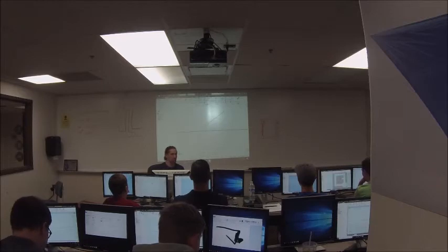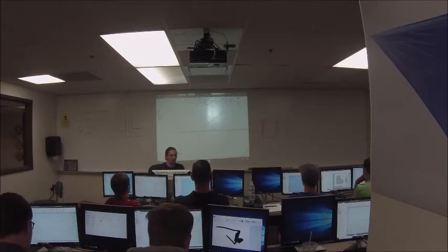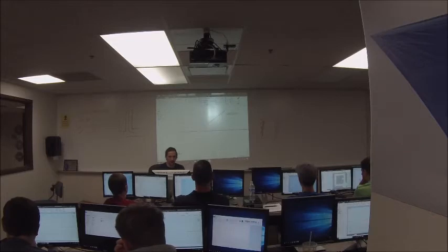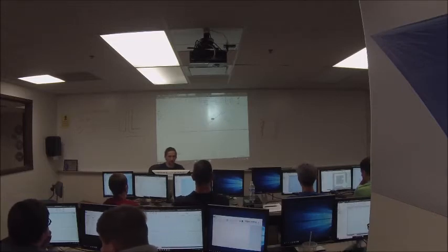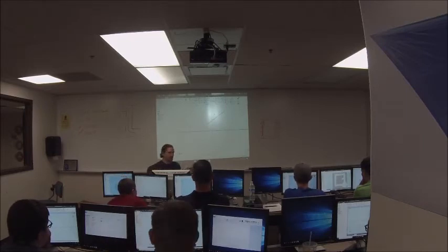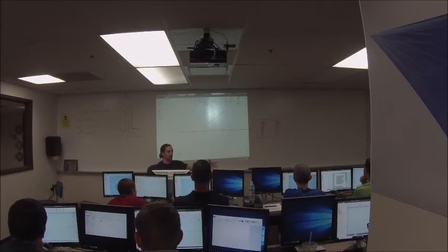There is also a midpoint in lines that you can snap other geometry to. Like if I want to create another line, I can hover over the midpoint. You see I get this green dot. And if I hover over the endpoint, I get this green dot. Otherwise, I just have a yellow dot. If I get a green dot, I can attach. That attachment, when I talk about attaching something, is actually automatically creating a coincident constraint.